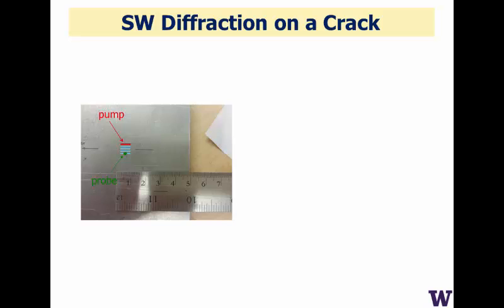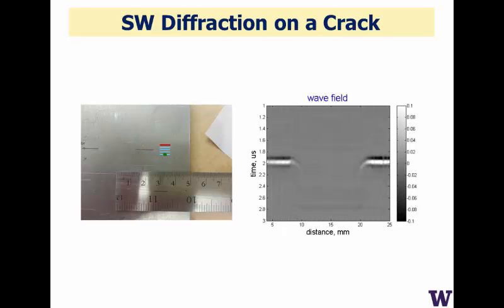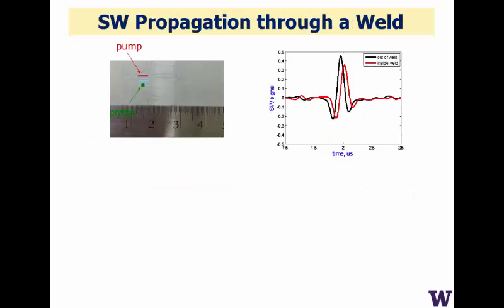We can then record the propagating surface wave along the surface and can do surface inspections of metals very, very quickly, very easily, again, non-contact. And here we just have a simple surface crack in a metal, which when we image is a piece of cake that you can see very, very simply. No problem at all. We can also look at things like welds.